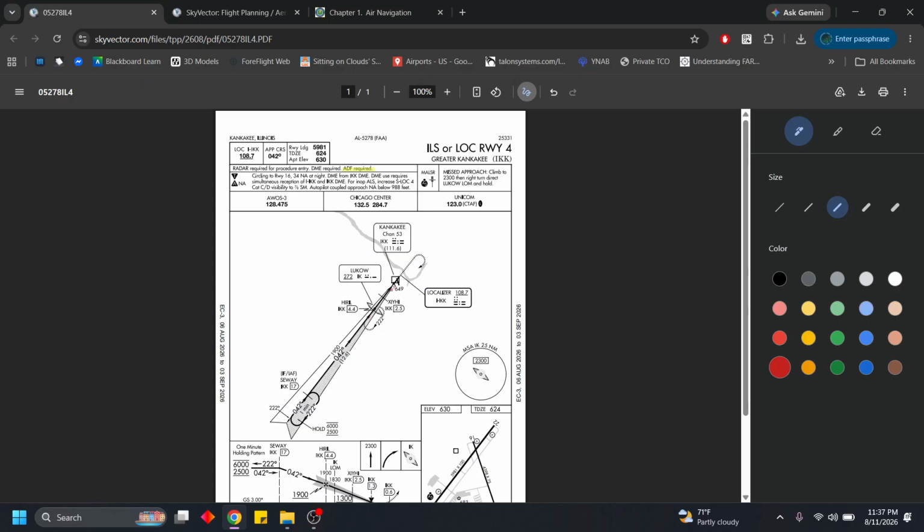for this hold itself. So the AIM gives us permission to substitute this entire thing, this entire ADF required here, with GPS, which is really cool. It means we don't have to have this installed on our aircraft, the super old antiquated equipment. We can just use the modern day GPS. Super nice.